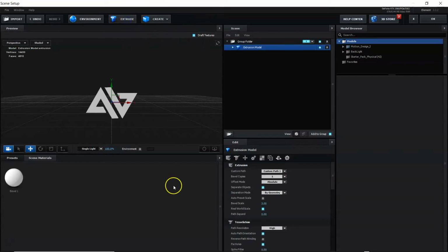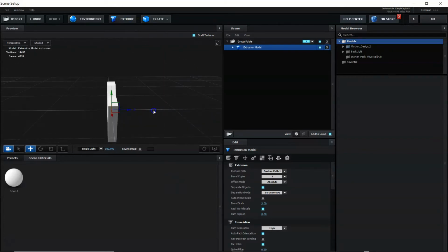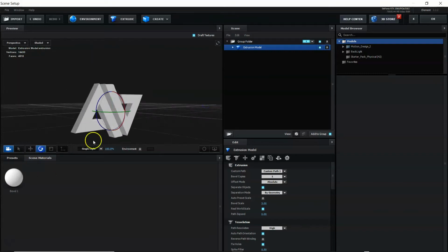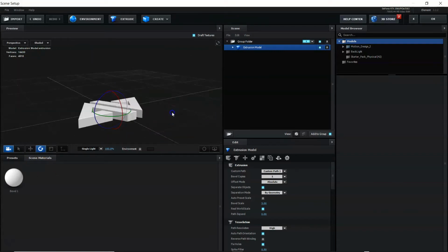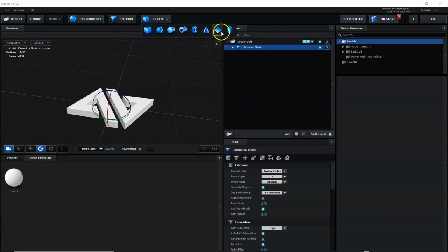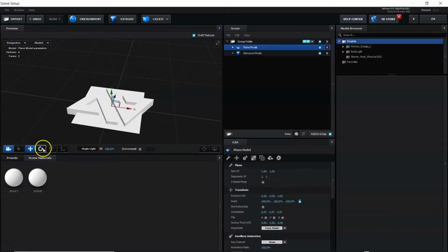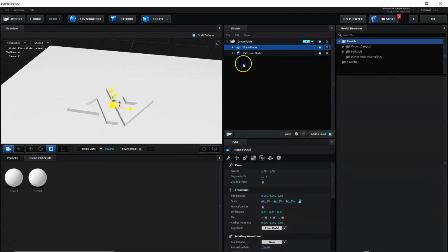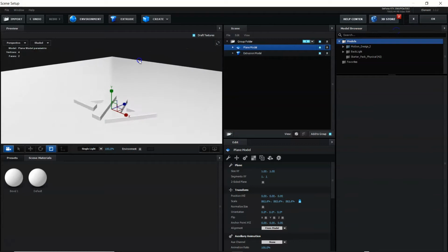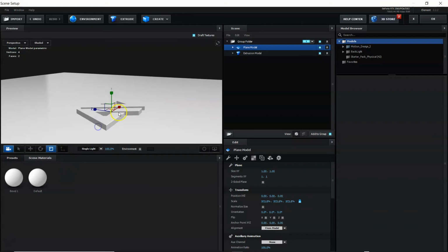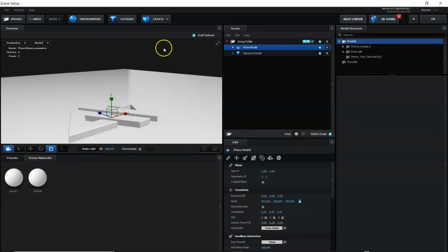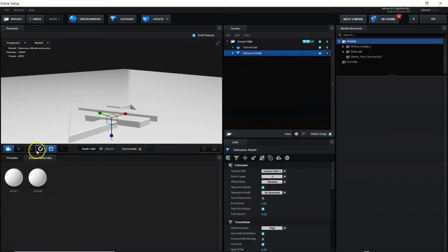If you click on Extrude, now you have your fancy logo in Element 3D. So great. Let's rotate this 90 degrees and we'll create a floor like so. Just bring that out a bit like that. A little bit more. And it's looking pretty cool. We'll click back onto our extrusion object, which is our logo, and I'll bring this up a slight bit like that.